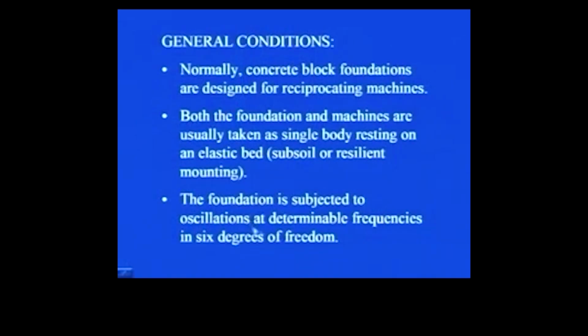So the foundation is subjected to oscillation at determinable frequencies. All the frequencies in these 6 degrees of freedom should be determinable. That is, we should be able to analyze what all the modes of vibration are and the corresponding frequency.